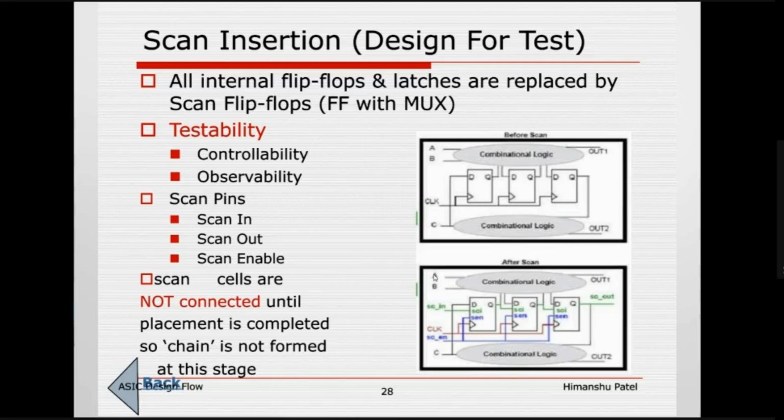Now you have given this design to the tool, and the tool is trying to create patterns and test this logic by assuming a fault at each and every node, everywhere. And it is driving that value through the scan input. A, B, and C you are able to put directly, the tool will force the value from primary inputs. What about the internal pins? If you want to place something in the D input, how do you place it?